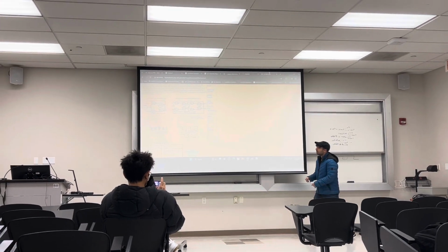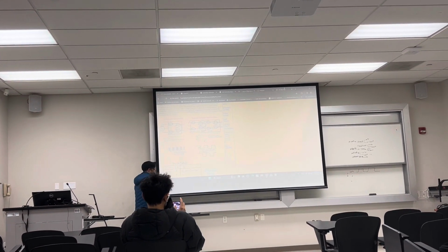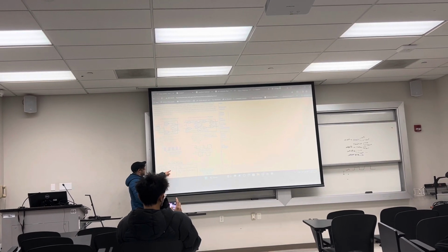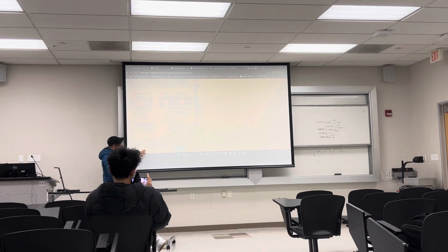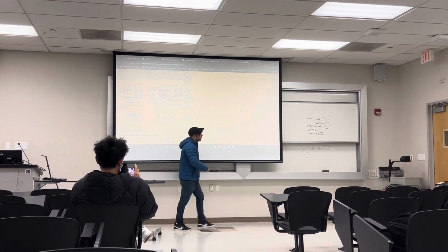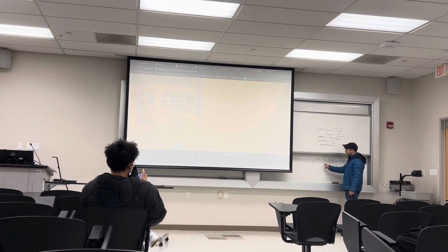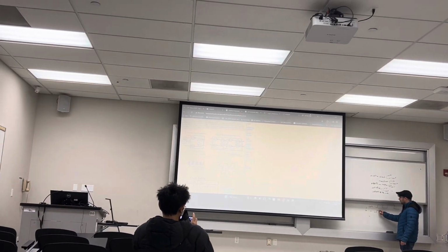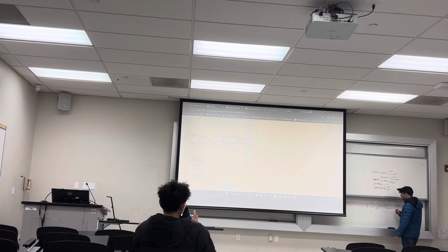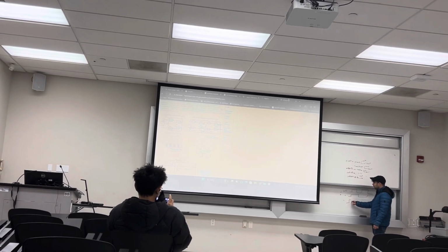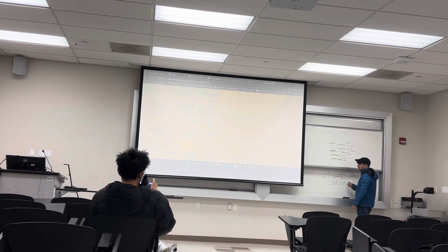I want to see that when J and K are 0 and the clock changes, Q doesn't change. All 4 conditions, and also that the output changes only when the clock changes. So make a condition where you will see all the conditions. One way is to put a J, then a K with a faster pulse speed, and a clock with a slower pulse speed compared to the two, something like this.